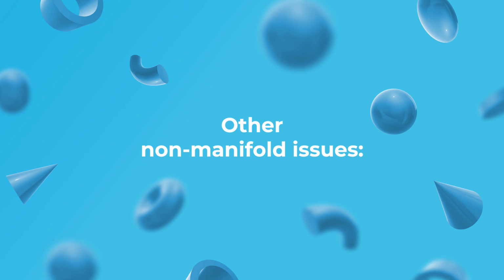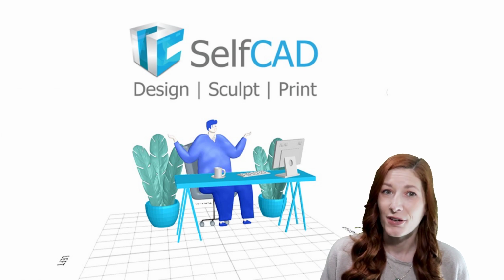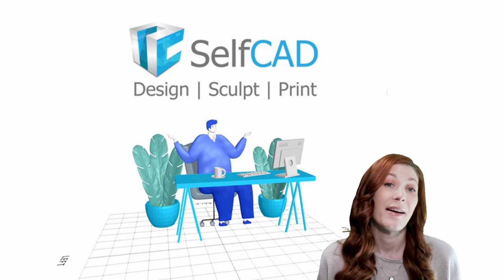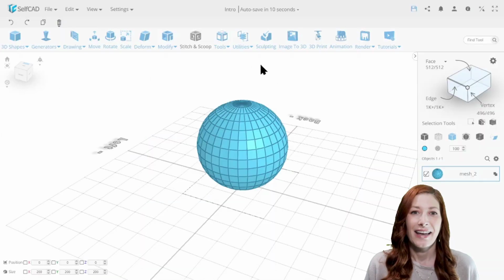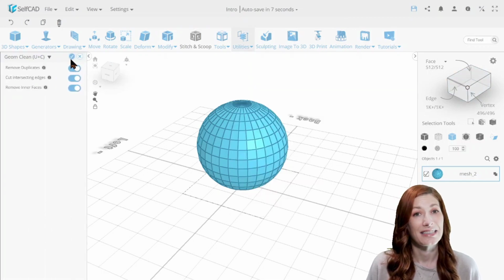Other non-manifold issues. There are other issues such as duplicate vertices. They are less common than the previously discussed problems, but you will still run into them from time to time. We have already discussed the solution to this problem in the previous parts, and you can fix them with the Geom Clean tool to remove such vertices.